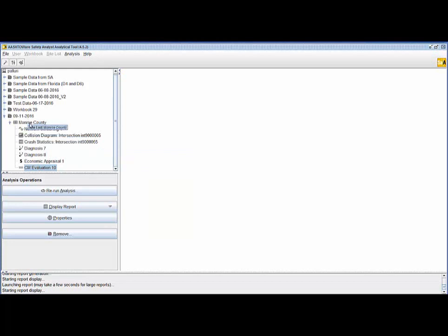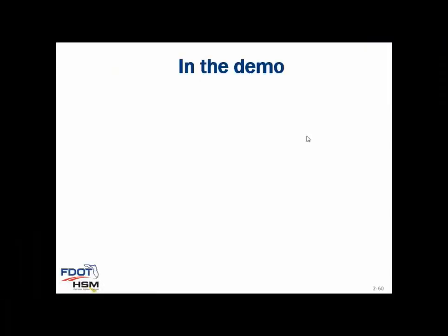we've created a new site list by name Monroe County. We then performed all the steps in the roadway safety management process. We started with network screening, and then the diagnosis, countermeasure selection, and then economic appraisal, and finally countermeasure evaluation. We have completed a quick demonstration of Safety Analyst. In the demonstration, we've created a new workbook and a new site list Monroe County. We have performed the network screening module.